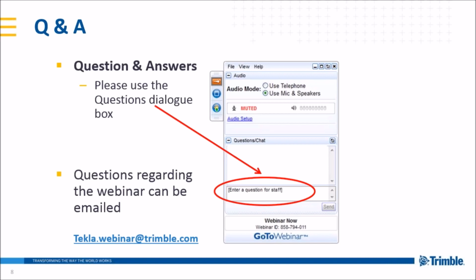But if you want, the user can change the values of the mesh. It's a little bit hidden from the user, but it can be changed in the code setup. For example, you can change the number of finite elements on the edge, or the minimal size of the element, or the maximal size. So it can be tuned, but it's not necessary. Okay, everything running automatically. Thank you.